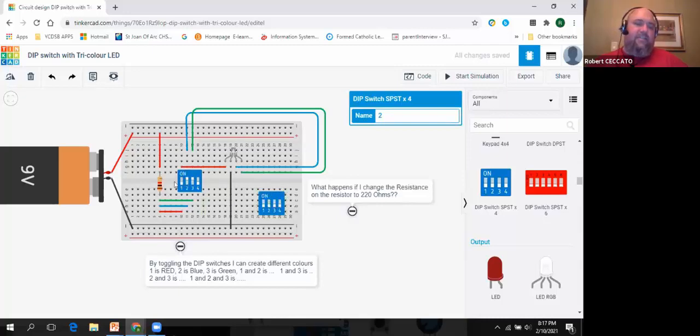that the dip switch is broken across the center of the breadboard, so that when power goes in on dip switch 1 and you turn it on, it actually flows across the breadboard to the other column to actually allow the circuit to go. Whereas if you do it like this, whatever happens on 25, all of 25 is going to have power, and we don't want that.